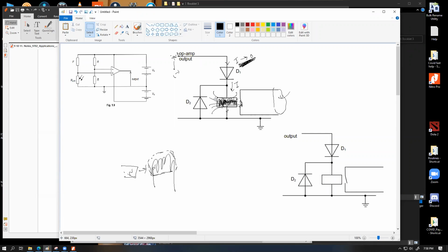Now, because this solenoid would not want to become demagnetized, it will produce a momentary high EMF so that it can maintain that current. This is what we call the back EMF. It is a very short-lived EMF, but it can be of a really high value depending upon the number of turns of this coil, which can essentially be a problem for our circuit, because let me show you why.